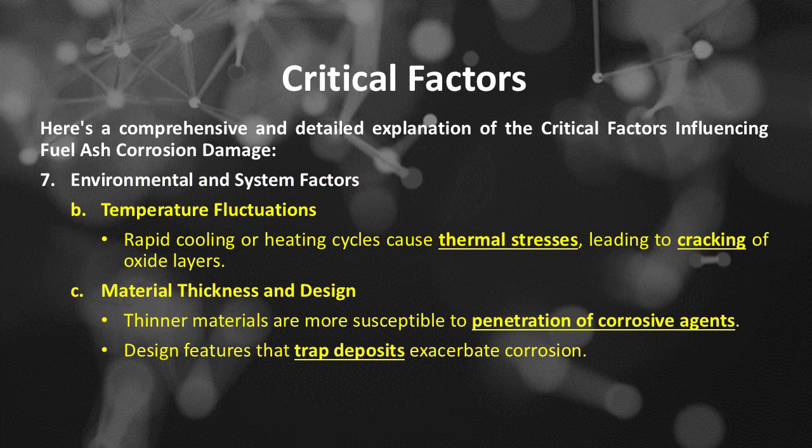Number B. Temperature fluctuations. Rapid cooling or heating cycles cause thermal stresses, leading to cracking of oxide layers. Number C. Material thickness and design. Thinner materials are more susceptible to penetration of corrosive agents. Design features that trap deposits exacerbate corrosion.